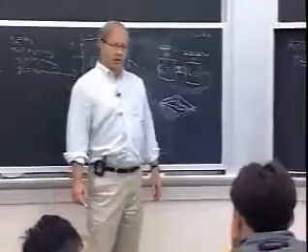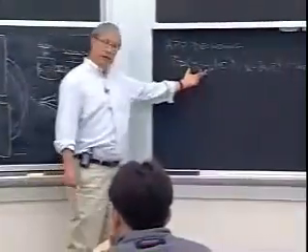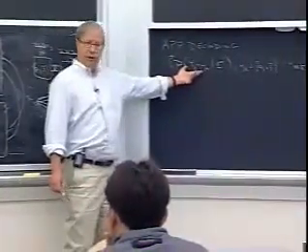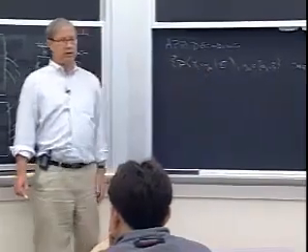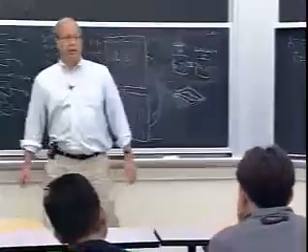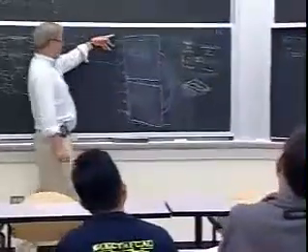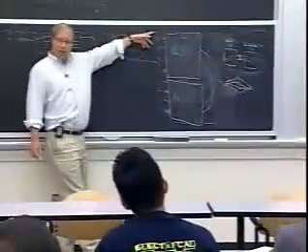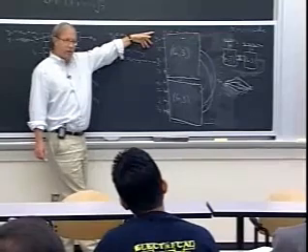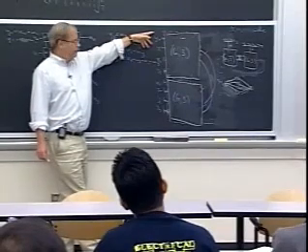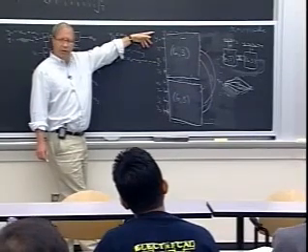The probability of it actually being the max is given by that a posteriori probability, and 1 minus that is the probability that it's anything else, and that's the bit error probability. So doing maximum a posteriori probability decoding on a bitwise basis is the way of minimizing the bit error probability.